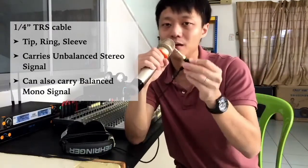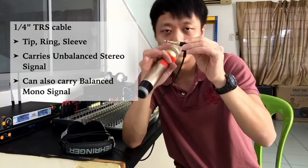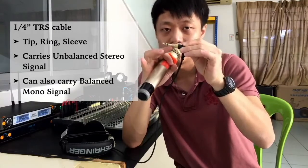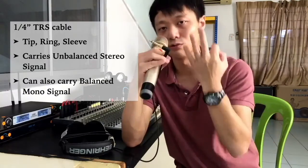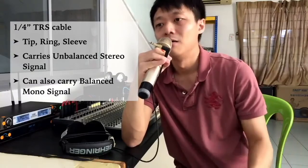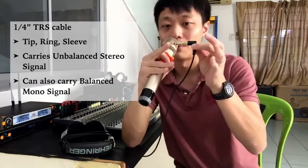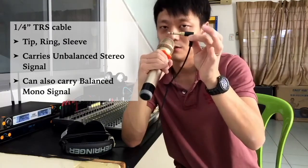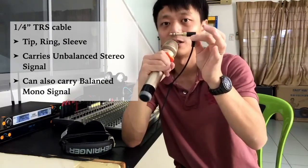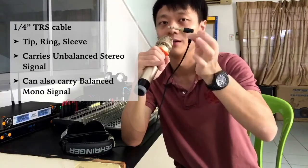And how do you do that? By connecting this T, this R, and this S, T for tip, the ring, and the sleeve, connecting them to the 3 pins on an XLR. Then you can use it to carry mono balanced signal, right? So one will be used to carry the positively charged audio signal, and the other one will be the negatively charged audio signal, and then the third one will be used as a ground, as a reference source.